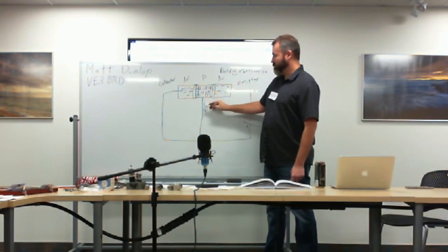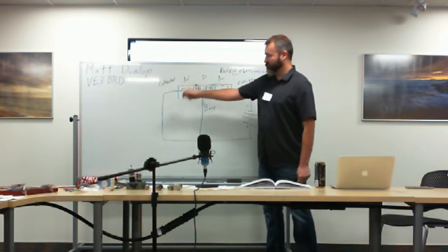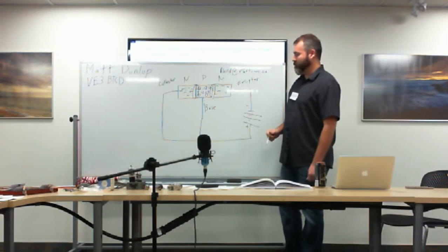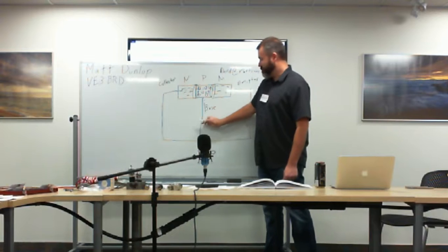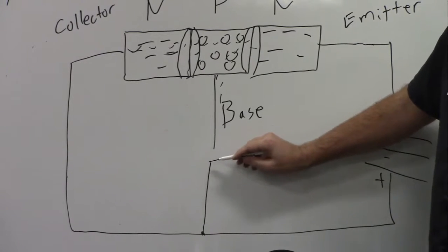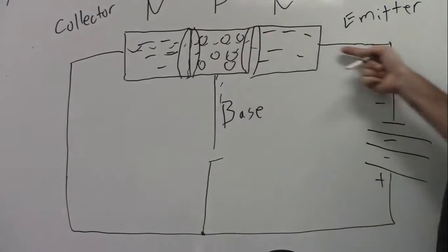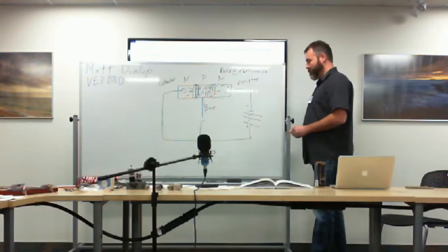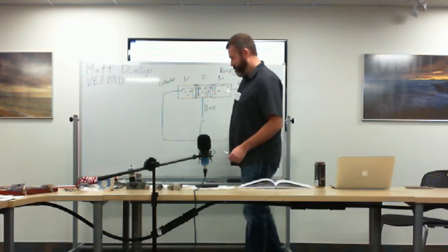So if we have enough voltage applied, positive voltage here to the base, it will completely break down this barrier and allow electrons to freely flow through the NPN transistor, and basically use it as a switch. So if you add something to break this connection here, then you can control this flow of electrons through these two gates. And for a PNP, it's very similar, except